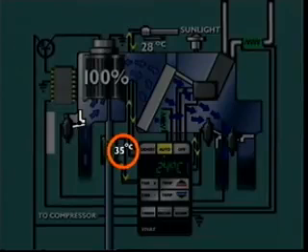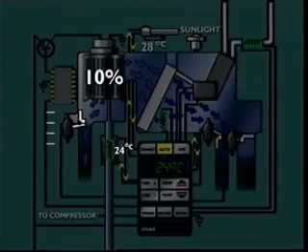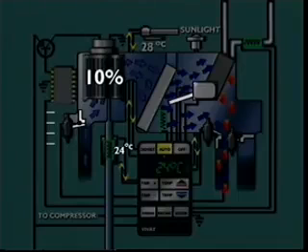The cabin air temperature is continually measured by the cabin air temperature sensor. When the cabin air temperature has been lowered to within approximately 2 degrees Celsius of the desired selection, the fan speed is gradually reduced. To achieve final control, the heater circuit may be opened and a blend door may be moved to direct some of the cold air-conditioned air through the heater core to provide fine temperature control. Both the fan speed and blend door openings are variable.